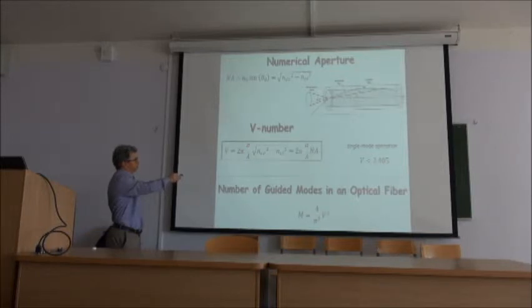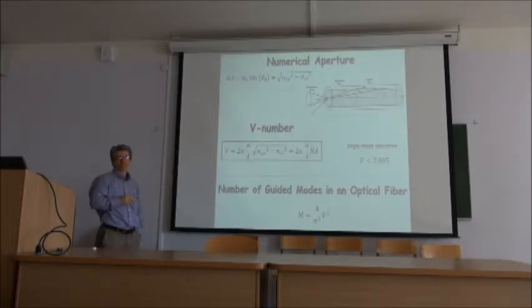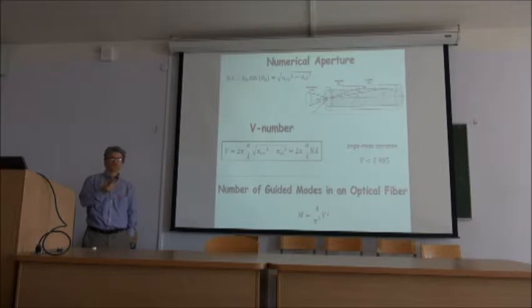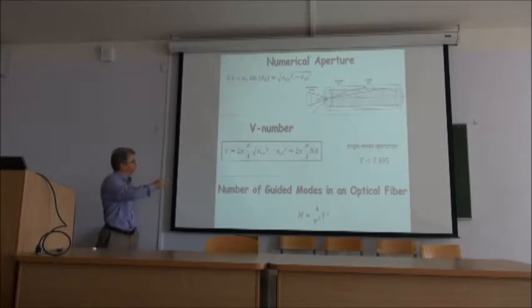We did have the thickness of the waveguide, and an omega over c, which is 2 pi over lambda. And what about the indexes of refraction? What we had there was film and substrate. And is it suitable only for a step index or for other profiles? This simple trivial expression is for a step index waveguide. If you have a graded index, you can still calculate the numerical aperture, and the expression is correct, but you no longer have this simple relation.